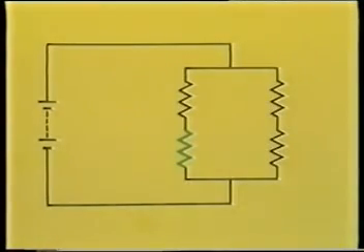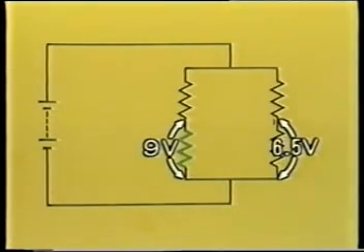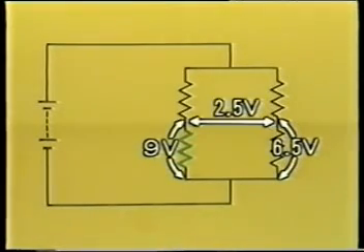Since we put a new resistor, painted green in the diagram in the lower left part of the circuit, the voltage changed from 6.5 to 9 volts. The voltage here remains at 6.5 volts. Therefore, there is a difference of 2.5 volts between the 2 points.